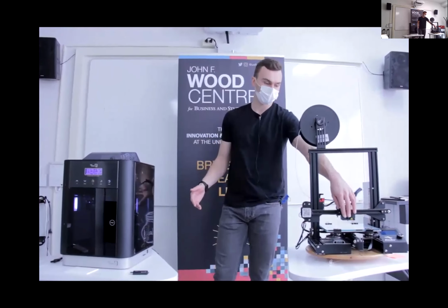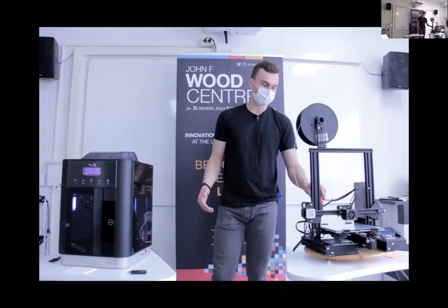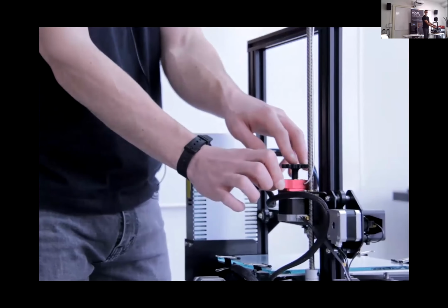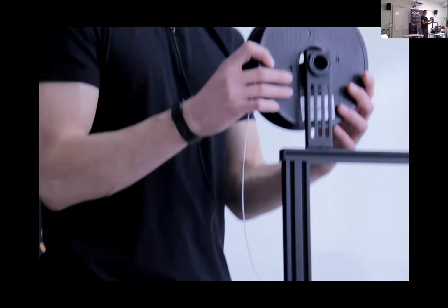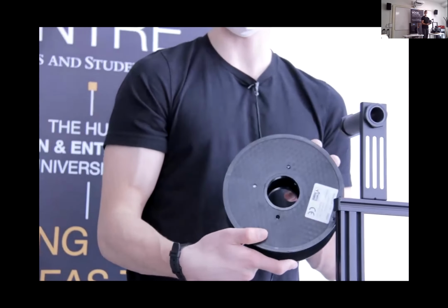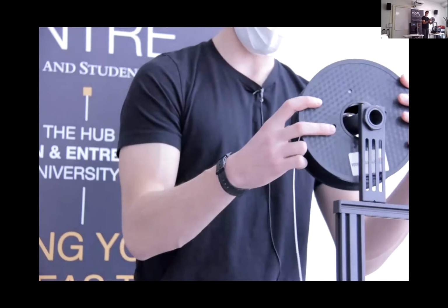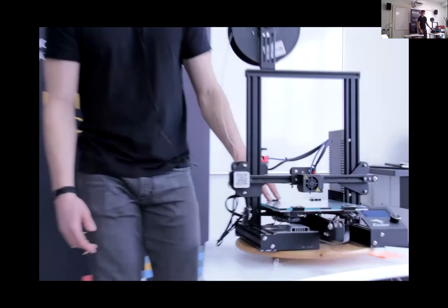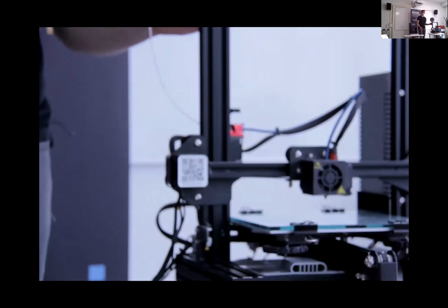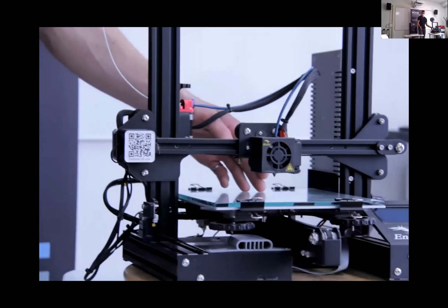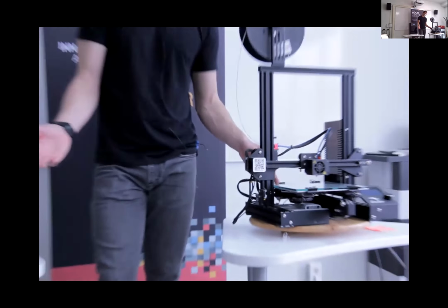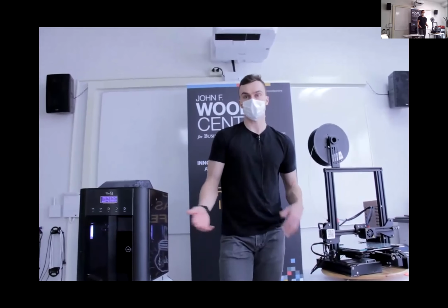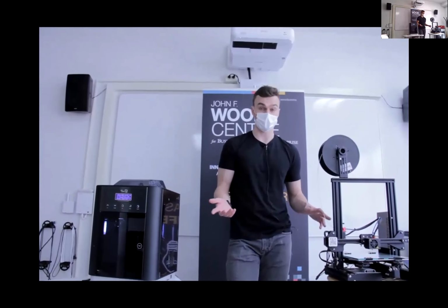They both have a hot end with an extruder nozzle. They both have some sort of extruder motor here with a clip that you need to press in when you're loading in your filament. They both use filament that comes on a roll like this. They both have a build plate with a certain area. That brings us to a difference though. The Ender 3 has a much bigger build plate than the Cubicon printer here, almost double the size in area. So that's a consideration you have to take into account when you're deciding what printer is best for your project.